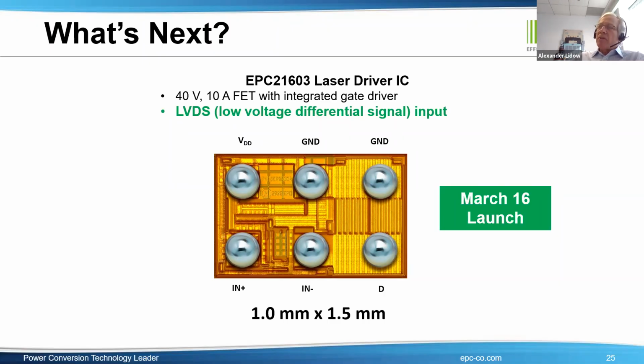The second biggest challenge, I think, for folks was handling these tiny little parts. Many people's manufacturing lines had to be upgraded. Their PC board design and design tolerances had to be upgraded. Again, we give a lot of guidance both on our website and through our field applications engineers on how to do that. And I think that once people overcame those two obstacles, they found that GaN devices were as simple as any silicon device to use.